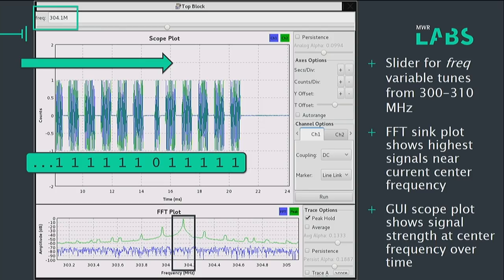And you can see the signal coming in at that frequency with, sure enough, longer pulses and shorter pulses showing the zeros and ones of the fan control. So if I was not a lazy person, I might take this opportunity to say, this is amazing, I've done it, I've got my own tuner. I can translate this on my own, and I'd get a paper and pen and sit down at my desk and write down every bit that came by as I push these buttons. But I'm still lazy, and we know where the frequency is now.